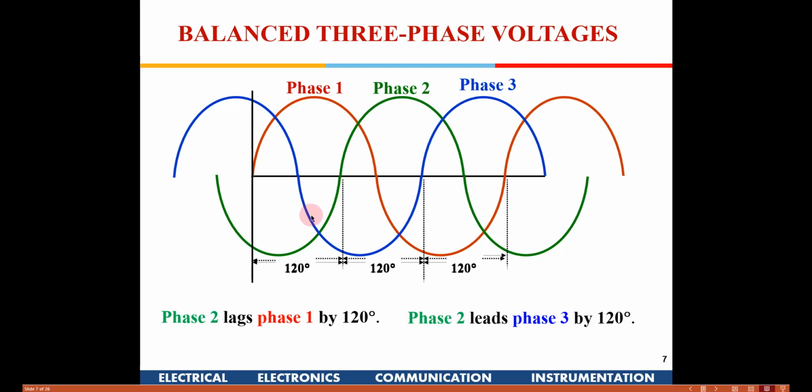So if you connect the other line, if you see here, this voltage is much higher than this peak, right? Because this is negative when this is. Similarly, when the green is going on the peak, you will find the other two are in the negative. Similarly, when the blue is in peak, if you try to drive a load between two phases, the voltage will be much higher.